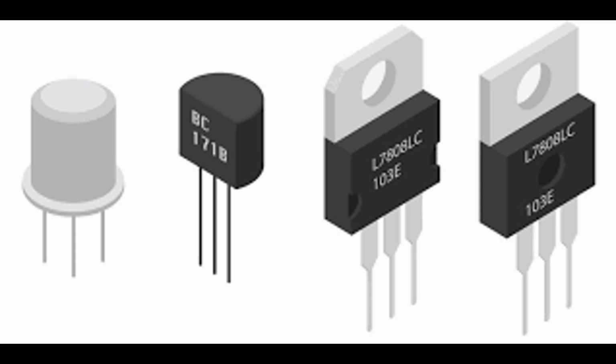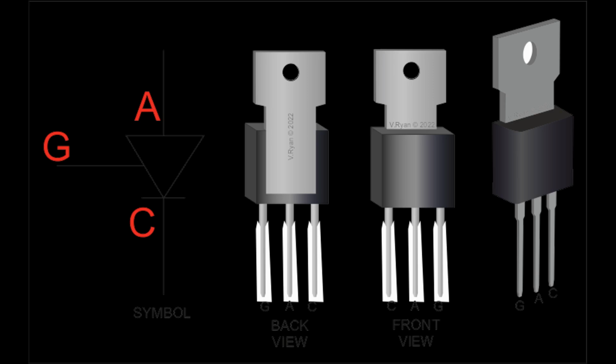Key characteristics. High power handling. Can manage very high currents and voltages, making it suitable for high-power applications. Fast switching. Faster than traditional GTOs due to the integrated gate drive circuit and low inductance design. High efficiency. Low on-state voltage drop and efficient switching reduce power losses. Robust design. Can handle high di/dt, rate of change of current, and dV/dt, rate of change of voltage, without false triggering.